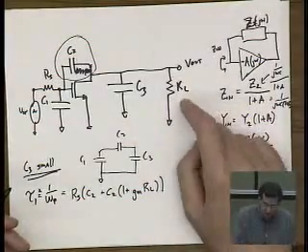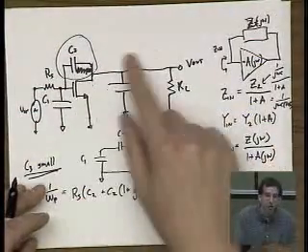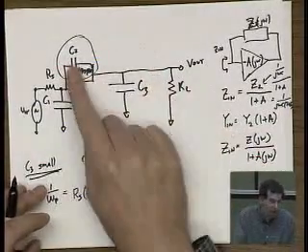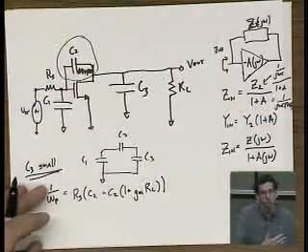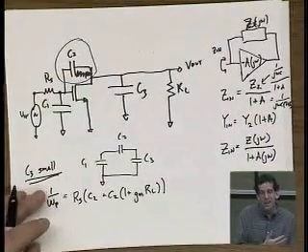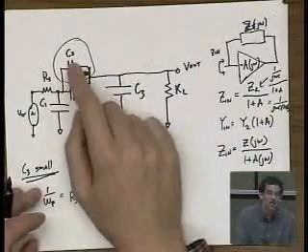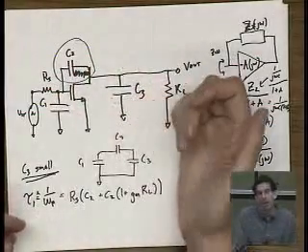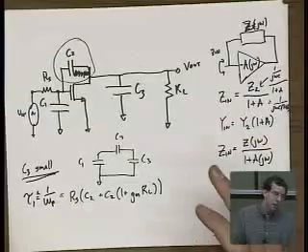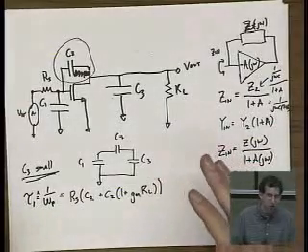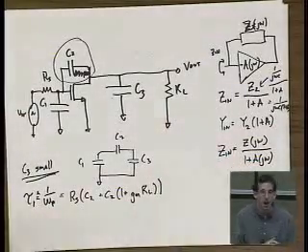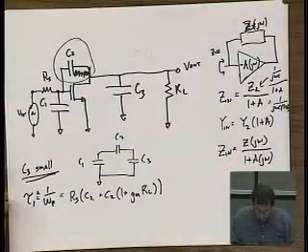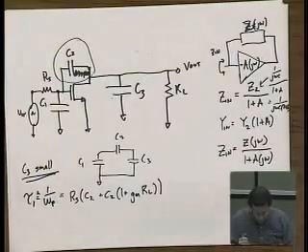This kind of approximation, assuming the DC gain for this Miller effect, is actually a pessimistic approximation. It makes this capacitor look bigger than it is, which brings a pole in. In actuality, this capacitor doesn't get multiplied quite as much, so that pole will probably be at a slightly higher frequency. Now, the caveat is that there are a lot of other approximations that you're making along the way that might be optimistic, so they all sort of jigger out. Okay, so that's the first pole.